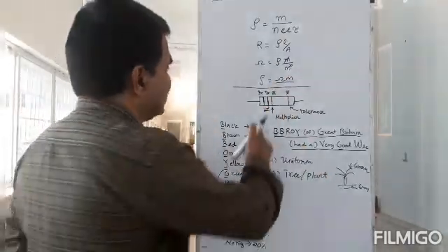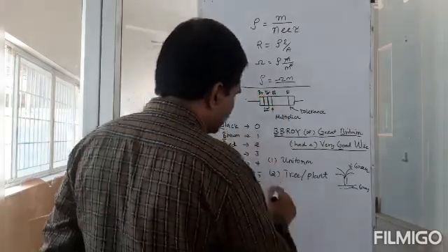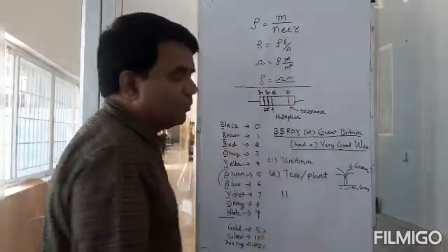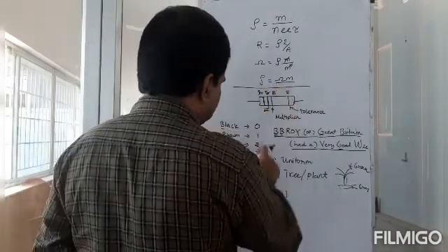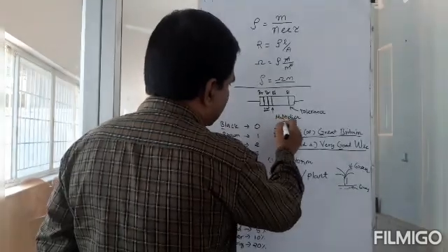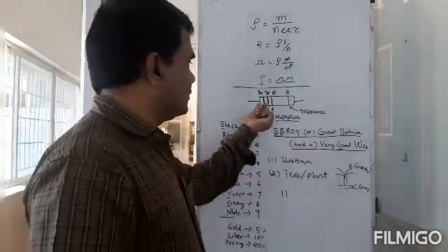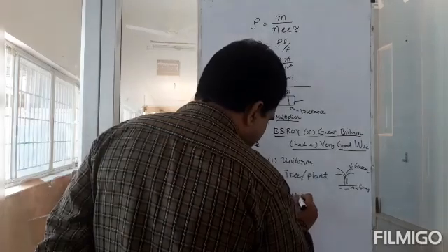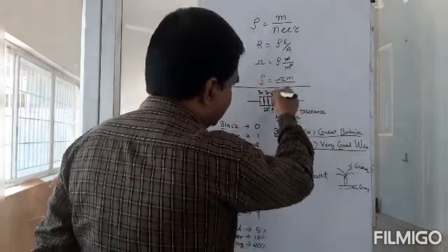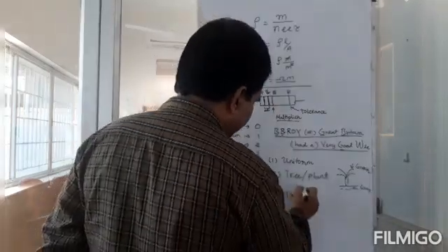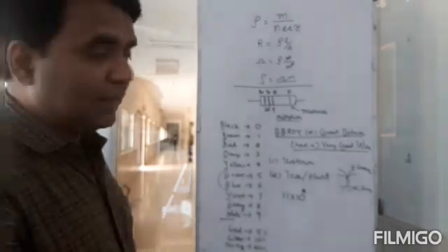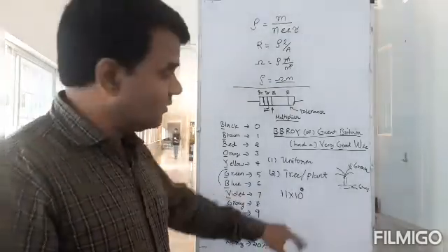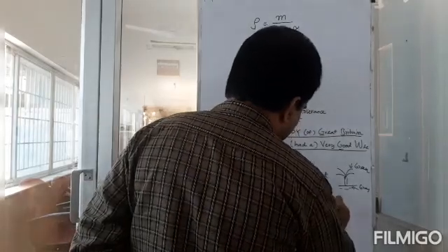Okay, first one, what's the value of brown? First one is brown. Brown is 1. Next is again brown, 1. Third is black. So that is actually, I said it's a multiplier. You need to worry only about the first two, and the third one is actually a multiplier. So 11 into 10 to the power, what is black? Black is 0. So 10 to the power 0 is 1. 1 into 11 is 11. So it is 11 ohms.